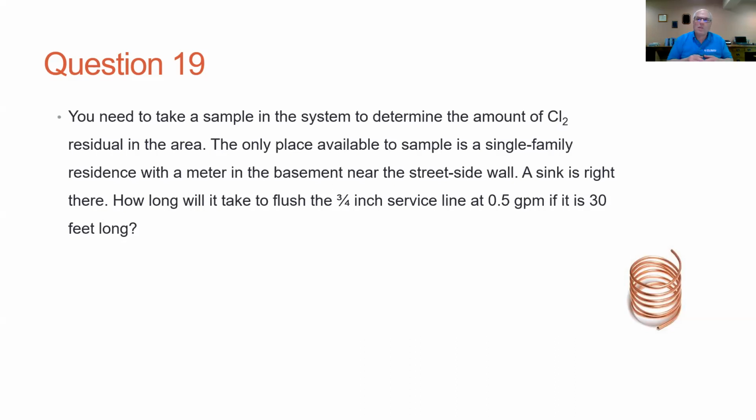We don't want to just turn on the faucet and grab a sample of the water that's been standing in the service line for who knows how many hours. We're going to flush that, but we don't want to sit there flushing it all day, make the customer nervous about paying too much for their water bill. They're wasting their water. But we want to flush it long enough and be able to tell them, I'm just going to flush it long enough to clear the main so that I can get the water from the main up to the house.